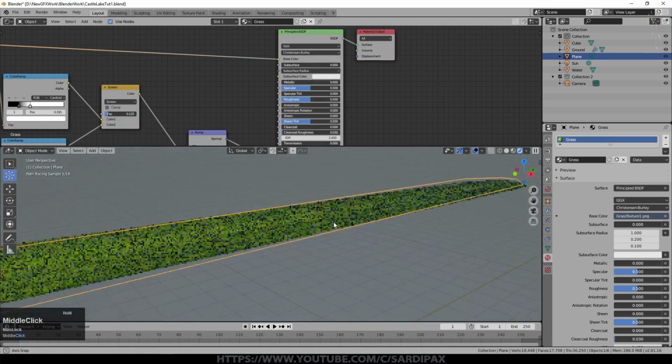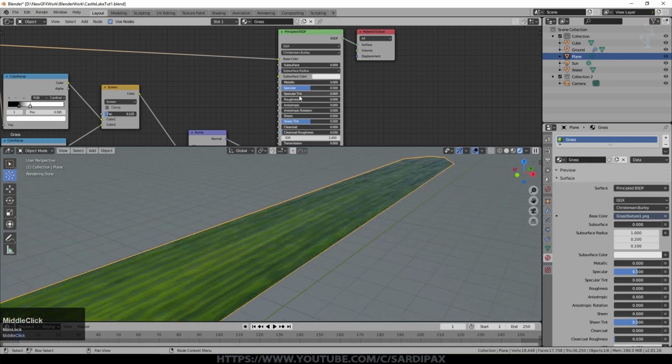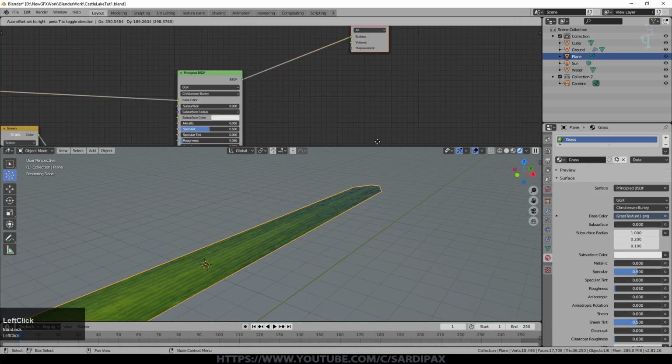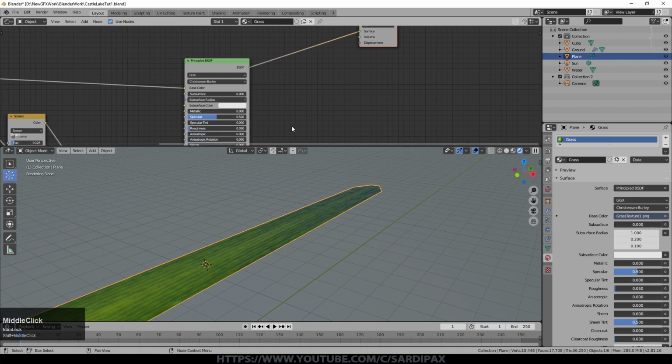And then we'll take our color back into here. Roughness is too high at the moment. If we take it all away, obviously it becomes a mirror and we don't want that, but we want a bit of shine on it, so maybe 0.05. We'll go with that for the time being. And again, there's some elements I don't feel work so well by using the principled shader.